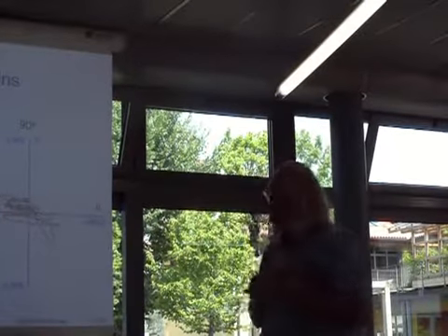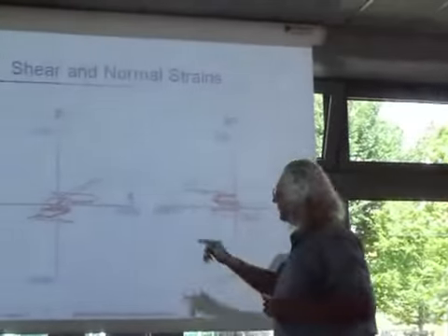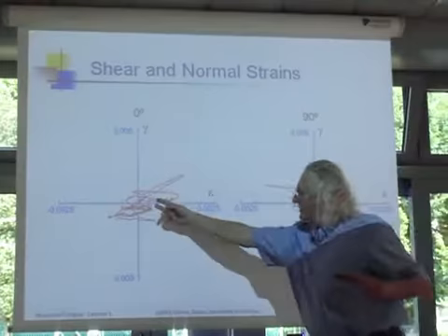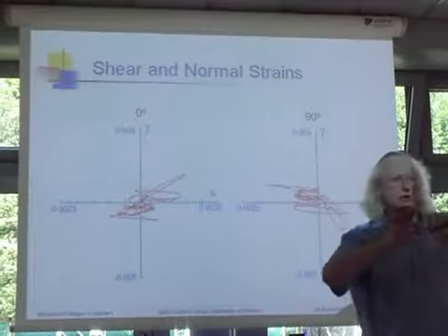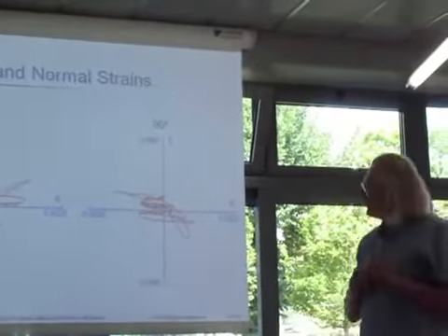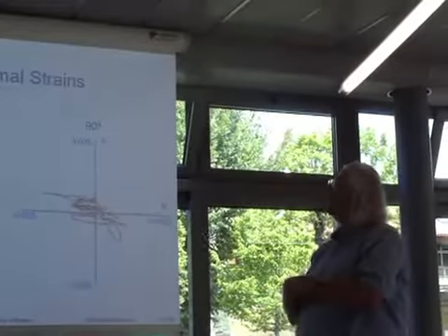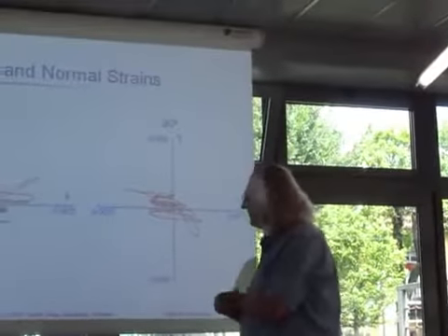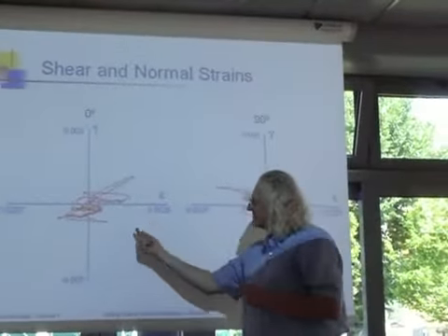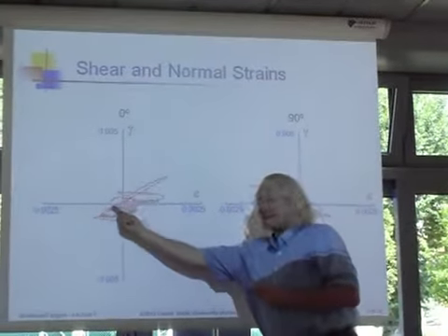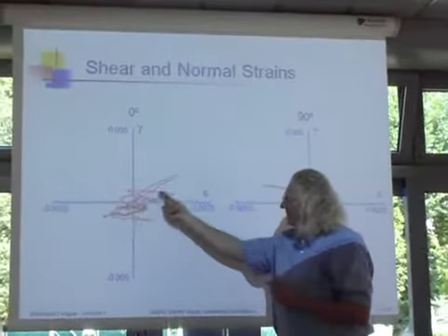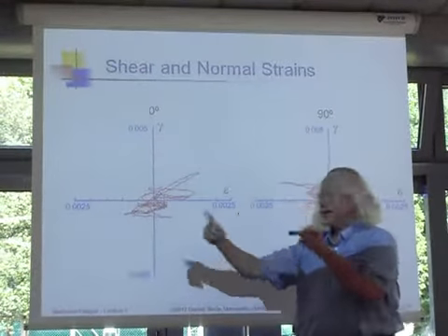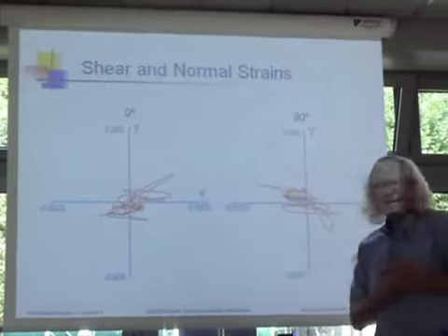So first we look on the surface, and we can look at the tension strain and the shear strain like that, and we look at a plane that looks like this at 0 degrees, then we see behavior that looks like that. And when you look at it in this plane, you can see this crankshaft sees a lot of bending loads like this, and it also sees sometimes twisting and bending together. Never pure twisting.